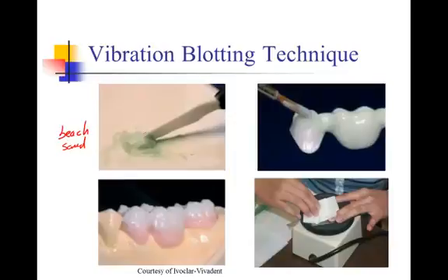And so an artist brush can be used to pick up this slurry and deposit it onto the shape that we want it to take. And we can make layers with various colors, and then use tapping by hand or a vibration platform, and that will cause the particles to flow together and pack more tightly and cause the excess liquid to rise to the top, and it can be blotted off or absorbed with some towels.